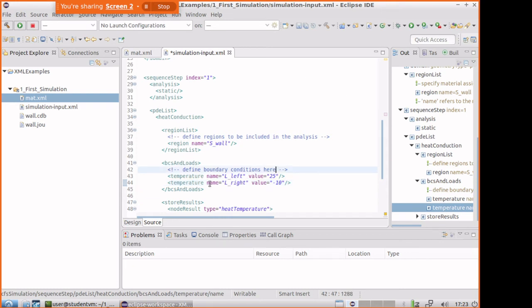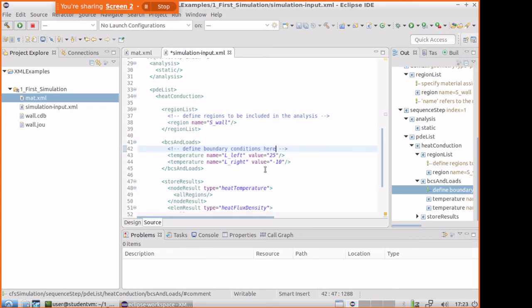Okay. We also have different boundary conditions available, but since we're running out of time, I will skip the more complicated ones. We also have some flux boundary conditions where you can define a heat flux vector through the surface, but you will encounter this anyway in the first homework, and I will show you another demonstration example where we specifically go into that detail. So now we have defined our boundary conditions.